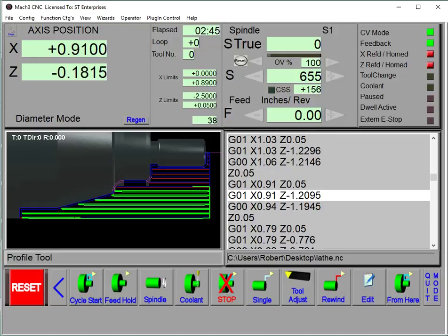So far I've done it right so far. You can always make mistakes in CNC. You have to double check. Therefore, I suggest that you dry run the program or cut it on a piece of wood or something like that before you really use your stock.